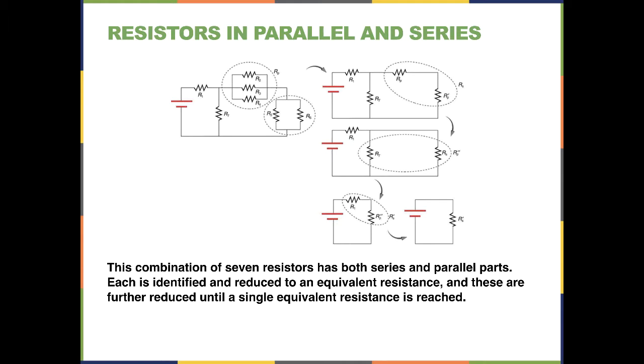So now, in this second diagram on the upper right, you see that you have simplified the initial 7 resistances to 4. And those two that have the circle around them are in series. And so you can turn that into an equivalent series circuit. I would have called that R subscript 2, 3, 4, 5, 6, because you're essentially changing the original 5 resistances to 1 resistance by just summing those two that you just found.